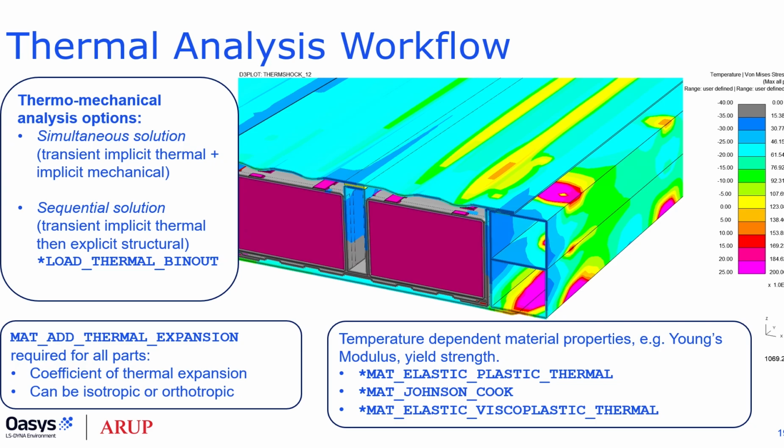There are several options for this available in LS-DYNA. The outcome of all this work should be a model that's capable of solving both the transient temperature distribution within the battery and the resulting thermal strains, and any potential damage within the battery that might affect its ability to operate properly. Arguably, the method could be extended to model the fire resistance load test, but because the thermal loading and temperatures are likely to be much higher, some further methods development might be necessary.